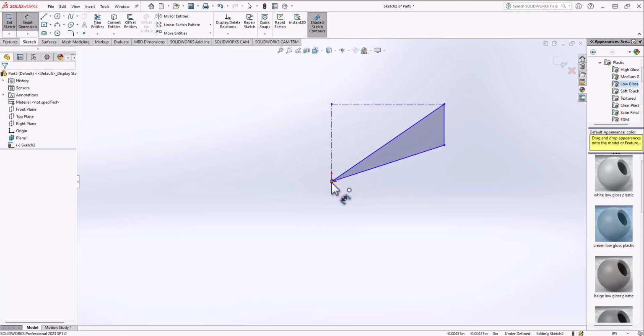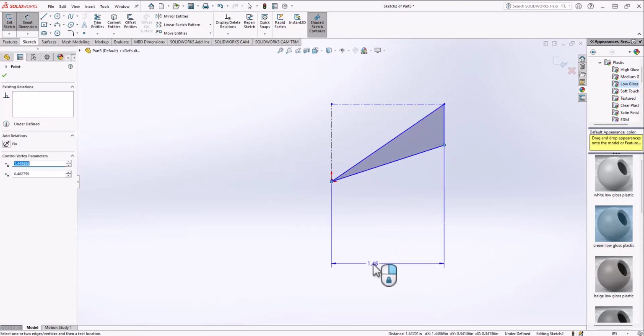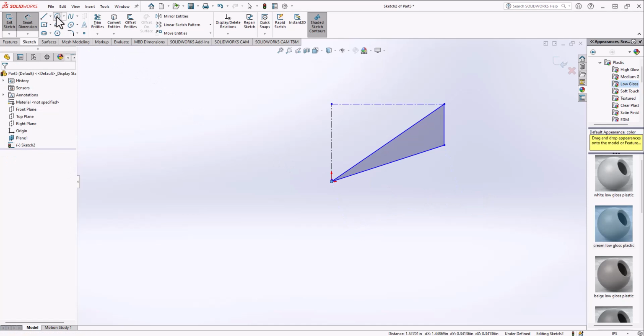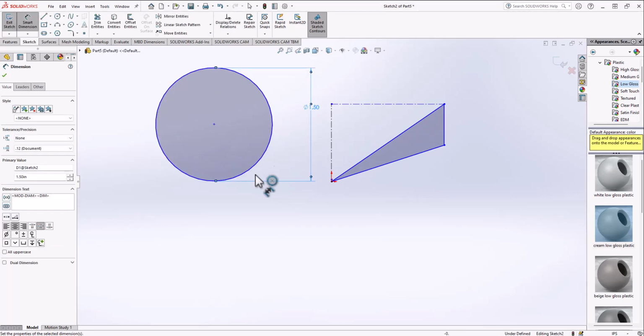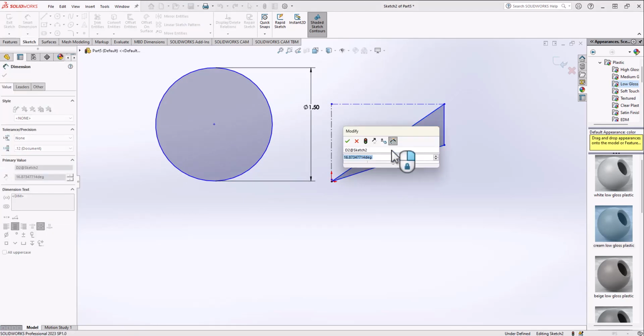What that essentially does is it lets you draw dimensions. So if you select 2 points and go down, it's the horizontal distance between them. To the right is vertical, and you can do a diagonal too, which is just the magnitude of the length of that line. And so you can do that for straight lines, or you can do radii, or I guess diameters in this case, for circles or arcs. And finally, you can do angles between things.